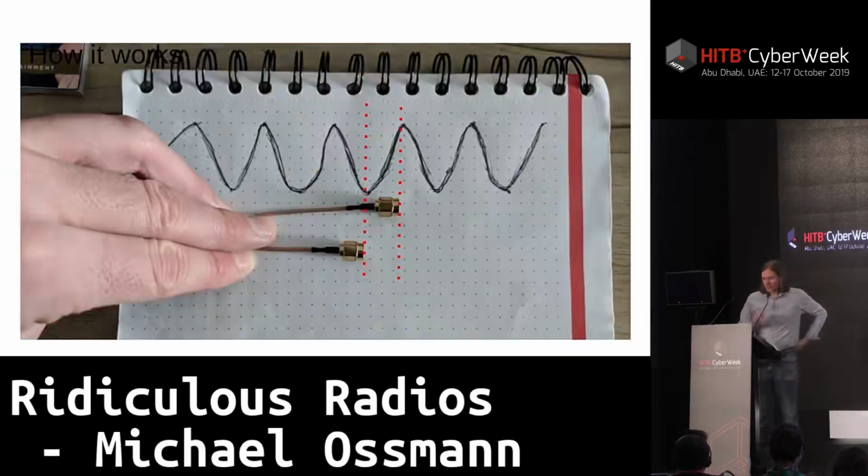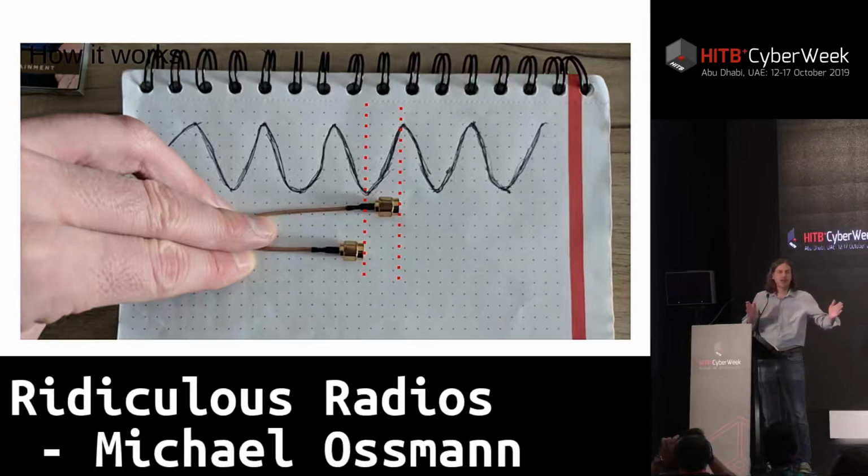Now, this is a really sophisticated plot here that Dominic drew to show how we actually introduce a phase shift over this signal. And the way we do it is with what's called a delay line. It takes a certain amount of time for a radio signal to be transferred from one end of a cable to another, right?